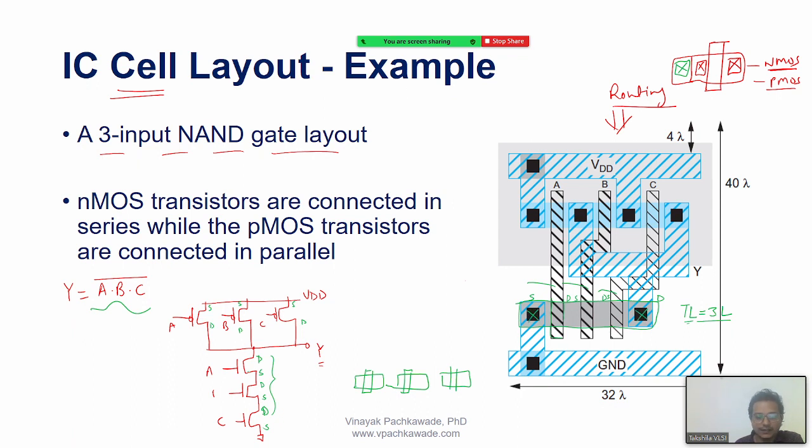So you see the drain and the source of this, there is a connection, so they are just in series, so right, this area also is common. So that is how these poly layers are separating the 3 transistors. You can also understand that that is one single transistor with total length equal to 3 times the individual length. So that's how I got this layer.